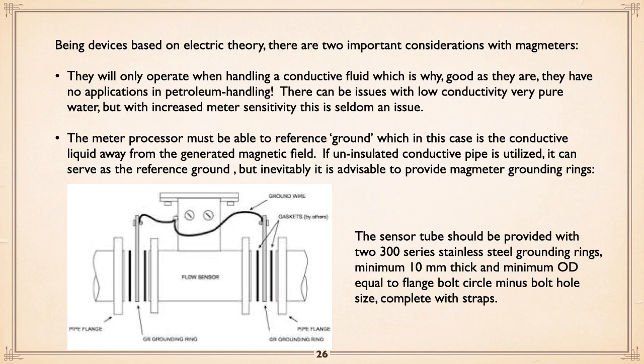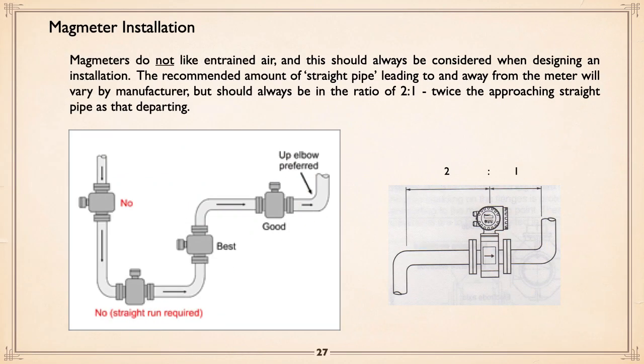for a mag meter works. Another thing, installing them: they don't like entrained air. So you can have problems mounting them vertically because with downflow, upflow is fine, but with downflow, air can be entrained and that'll throw it.